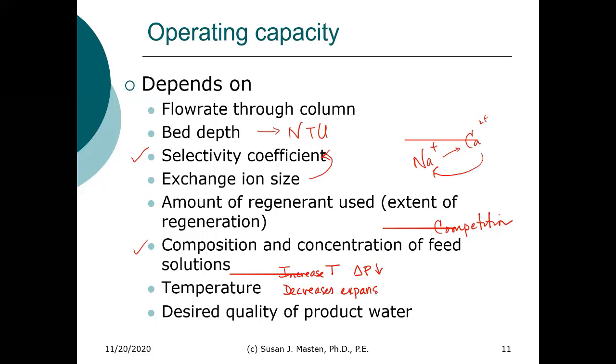expansion during backwashing. With an ion exchange resin in a column, we operate these very similar to the way that we operated our granular media filtration systems. Just as in filtration, when we backwashed, we wanted to expand the filter bed, we do the same thing in an ion exchange system.